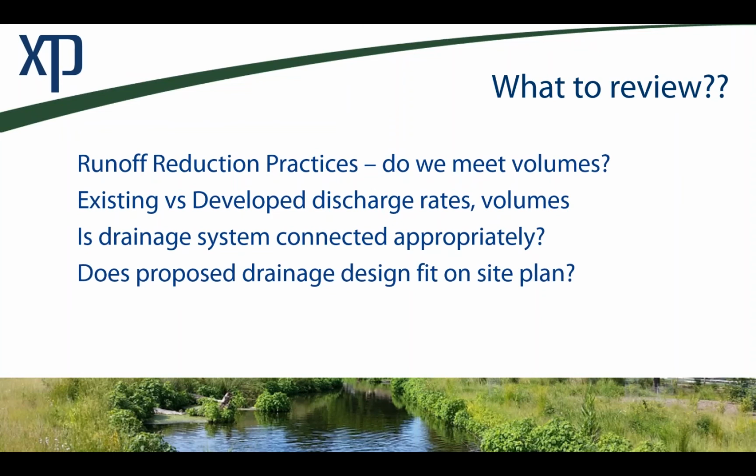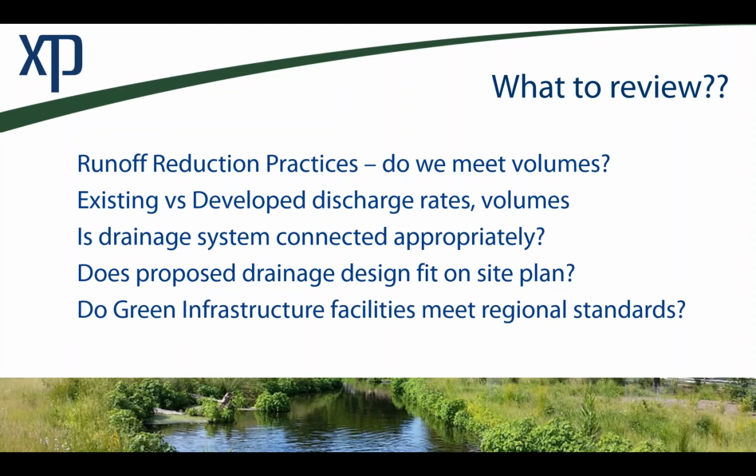Another one might seem obvious discussing it now, but in practice can really slip through the cracks. Does the proposed drainage design actually fit on our site plan? This is a bit of that back and forth. The drainage team says, here's my proposed pond, here's my proposed rain garden. This is how big it needs to be to control that runoff reduction water quality volume, or perhaps that 100-year event. Great. So you hand that spreadsheet off to the site team. What if what's in that spreadsheet really doesn't get represented in that plan? Okay, that's an issue.